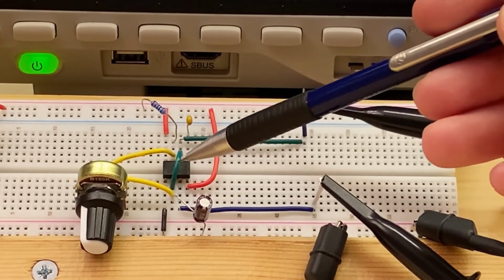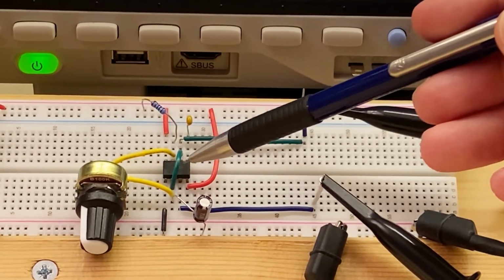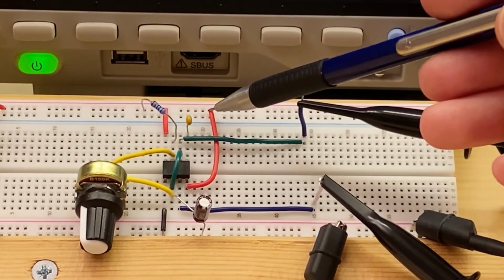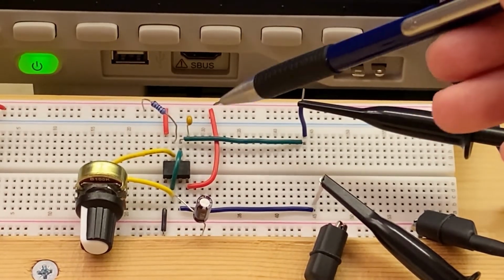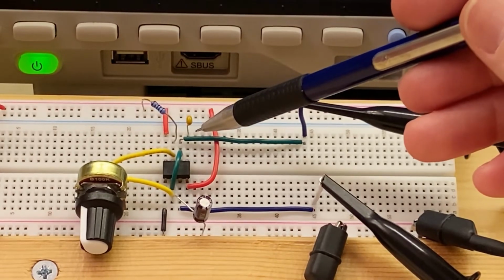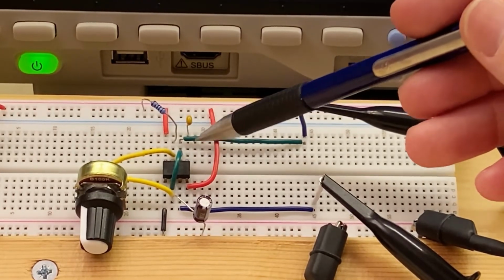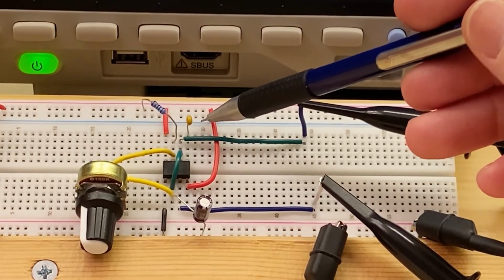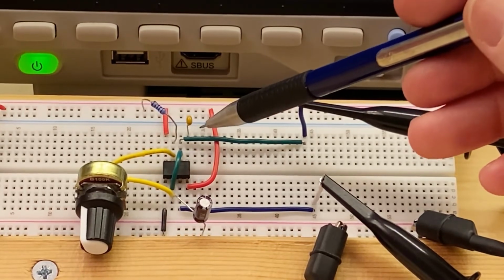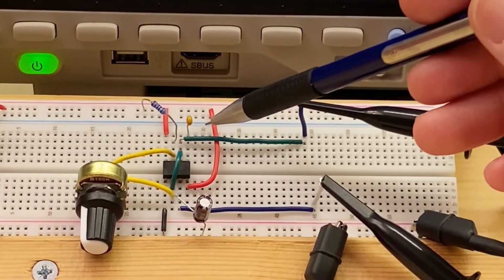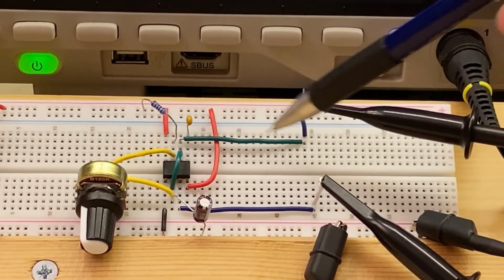And you can see pins 2 and 6 are tied together, and our reset is tied up high so that our chip cannot reset. I've also added a little 0.01 microfarad cap on pin 5 that goes to ground. And this has been added because the data sheet suggests to add one, as it helps with the operation of the chip.